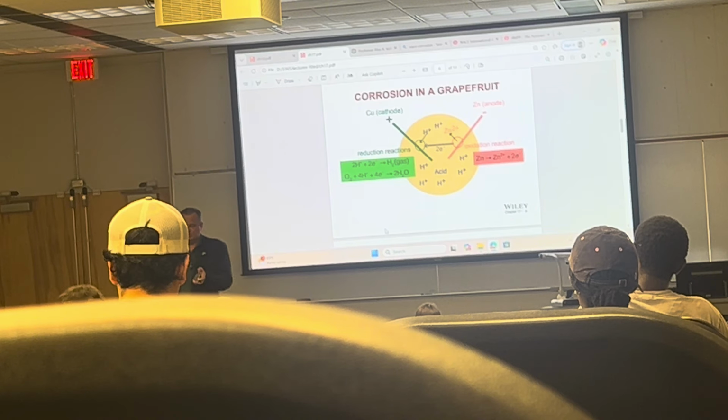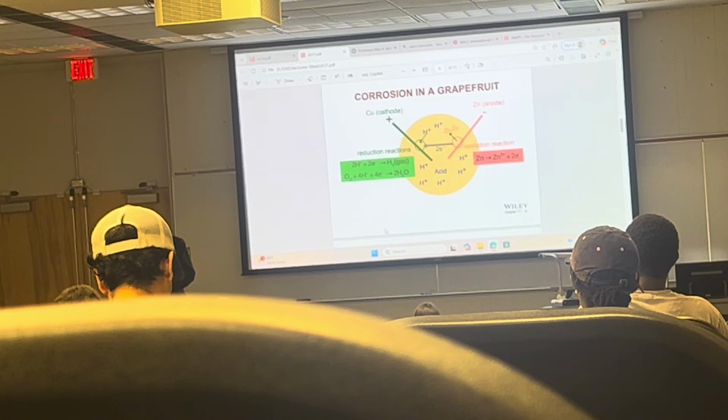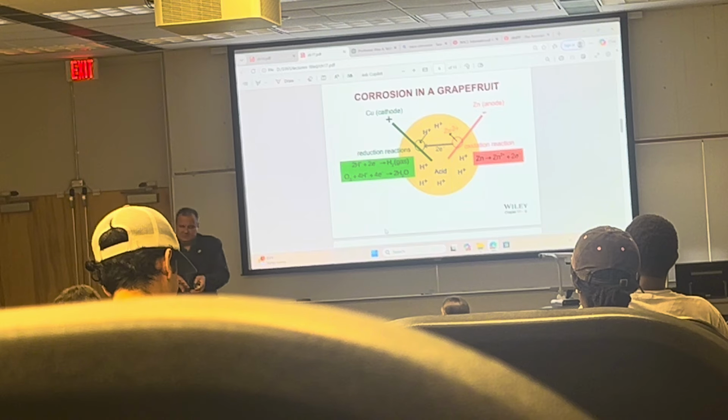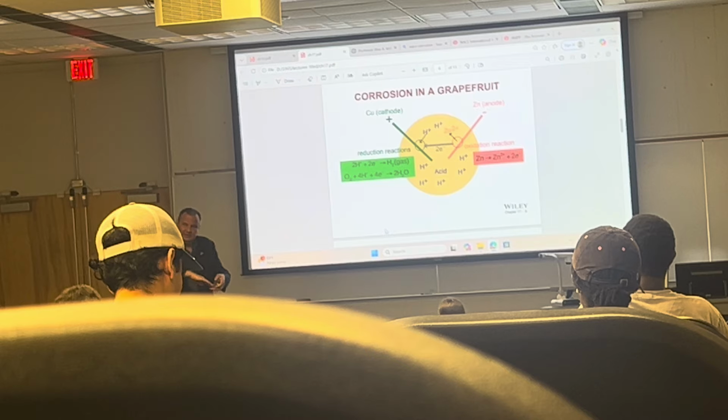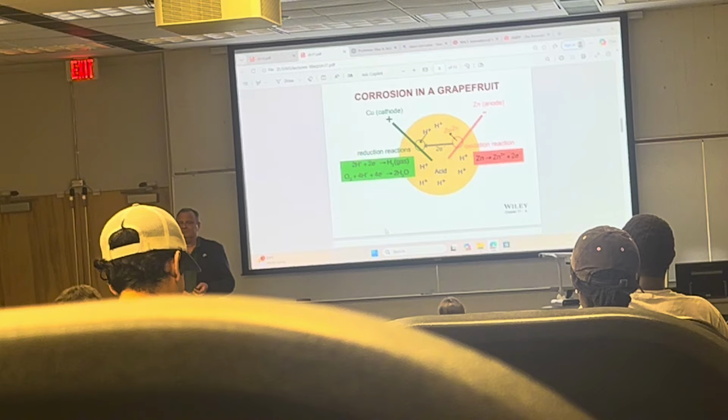The balconies are sloped towards the building. And I guess whoever made that, so why not slope them out evenly? So when it rains, it pours, right? No, they sloped them towards the building. So the water runs towards the building, and it's supposed to run sideways into the specially designed cast iron pipes, and those cast iron pipes were gone since 1962.